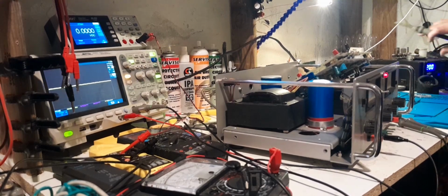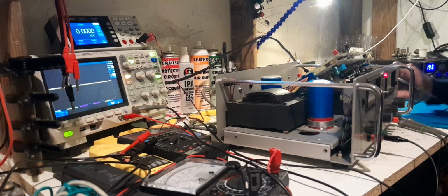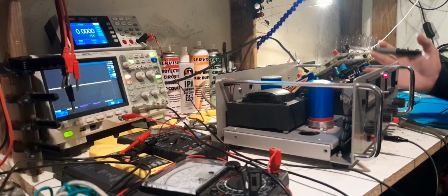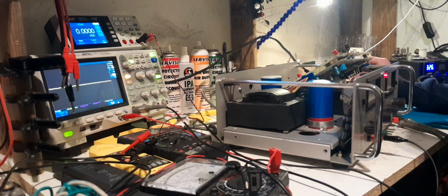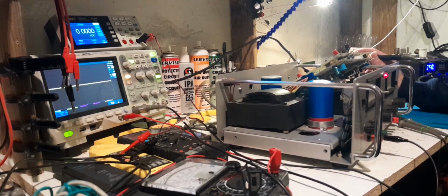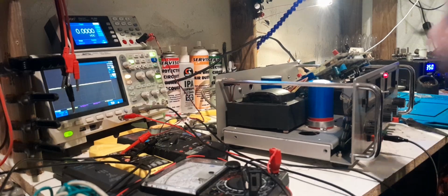And I think it'll become pretty apparent really quick why. Because I think if I keep trying to do what I'm doing, trying to compensate op-amps, I don't think we're going to have any luck. And I think if I was to compensate it to the point that I got rid of all the noise, the slew rate would be like 1 volt per second. I'm not even being funny. And we'll get to exactly why that is in a sec. I'll show you. It's actually quite comical.